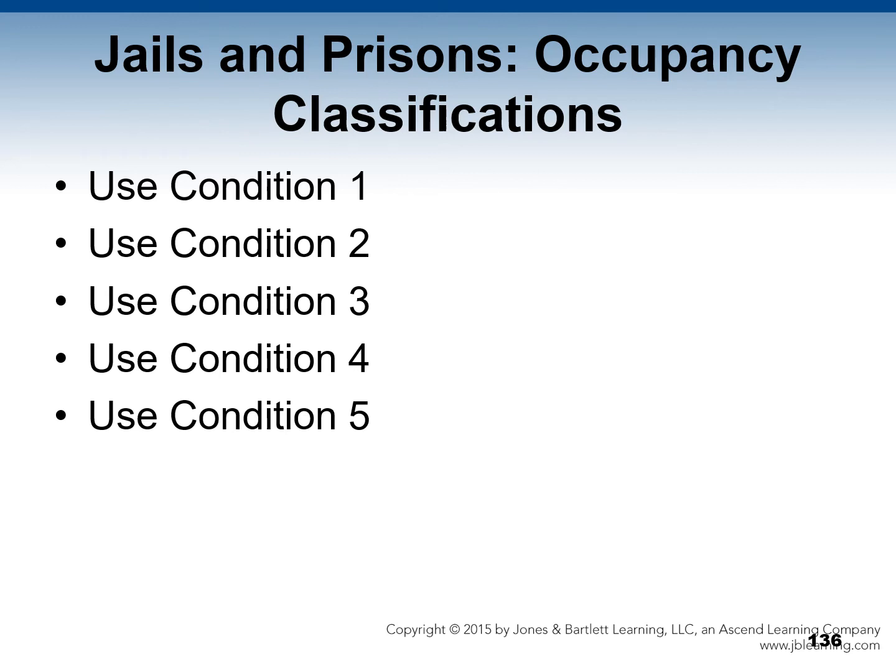Use condition 4 is free movement permitted within an occupied space within a smoke compartment. Movement to other areas of the smoke compartment or other smoke compartments is by remote control release. And use condition 5 states that free movement is restricted from the occupied space. Manual release is necessary to allow movement from the occupied space to other areas of the smoke compartment or other smoke compartments.